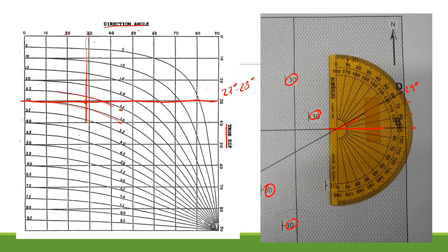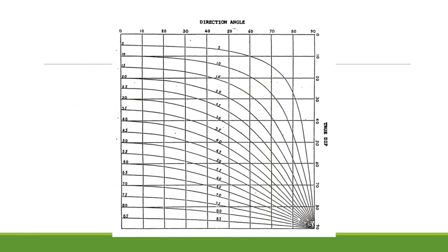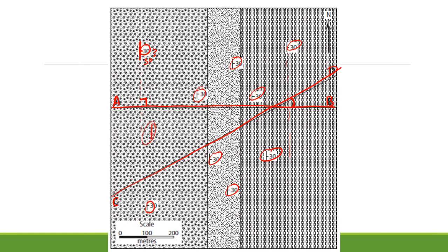So then you do your cross section just like you did before. You line up your piece of paper along here, like that. You mark off where those boundaries are. But now when you're drawing your cross section, you will mark your boundaries onto there, and now you're drawing down an angle, and this angle will now be 27 degrees. So very similar to before, but now it's at 27 degrees. It doesn't make a huge amount of difference because we've only got a relatively small angle in here.